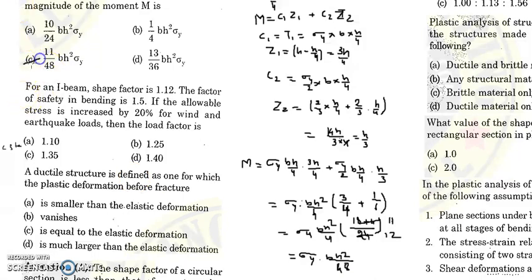You have to solve by yourself. You need to understand each step here. I hope it's clear. So now here, for an I wave, shape factor is 1.12. Okay, fine. Shape factor is 1.12. The factor of safety in bending is 1.5. If the allowable stress is increased by 20%, okay, for wind and earthquake loads, then what is the load factor